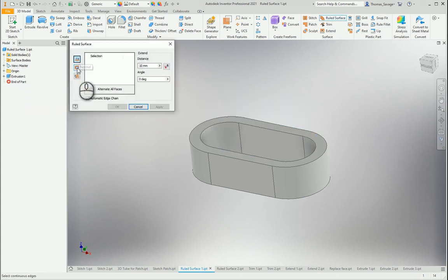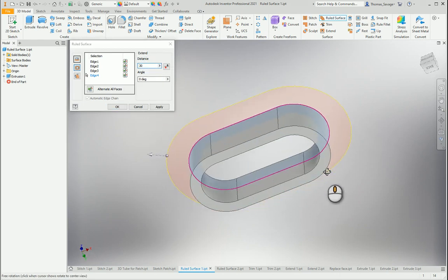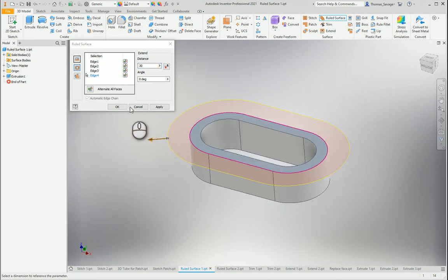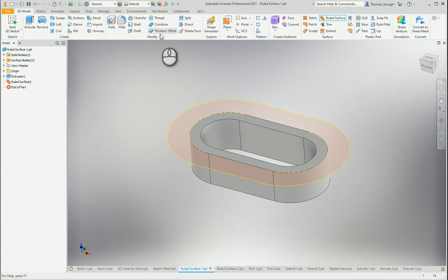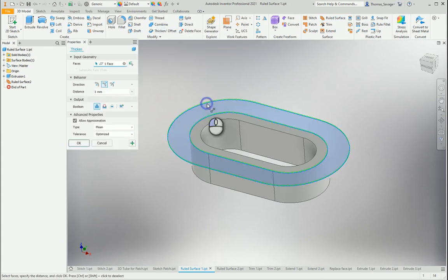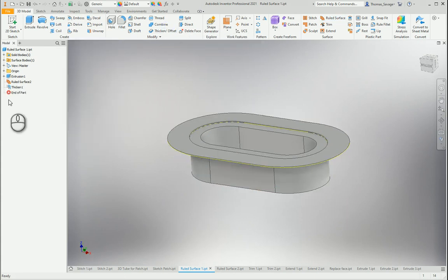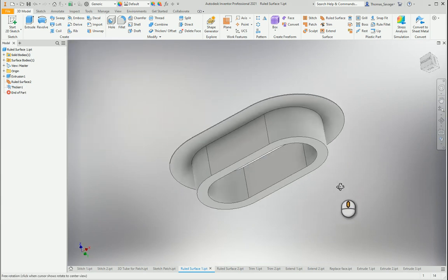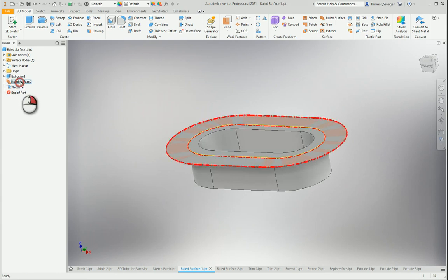That was normal. Now we'll go tangent. For tangent, I'll select the outside profile to show, and we will do 30. And as you can see, it's gone outwards instead of upwards in direction. Click OK, and the same again. Thick and offset, just an example. If you wanted to put a flange on, maybe, you'd find that's the best way. That's gone in the one direction. That's one way, and then if I delete this ruled surface.